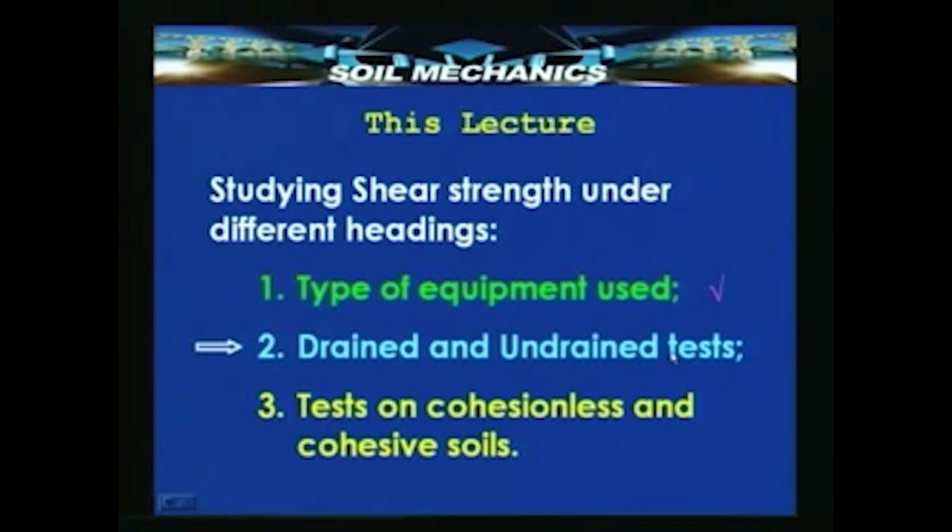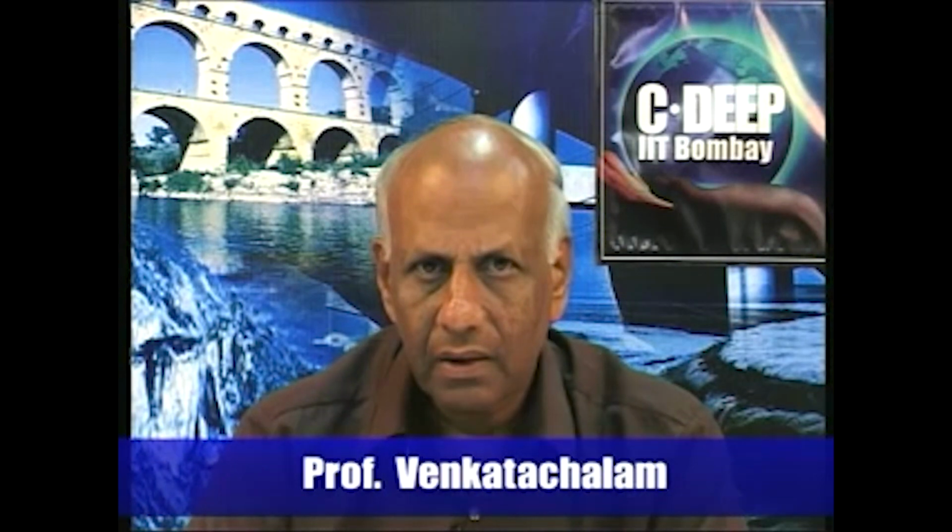Now, it is very well known, we have discussed it sufficiently often, frequently in both my lectures on consolidation as well as in this, that when a soil is saturated and when a load is applied, be it compressive or be it shear, whenever a load is applied, if the drainage is permitted, then the load gets transferred to the soil grains as intergranular stresses. Otherwise, they remain as neutral stresses in the soil in the form of excess pore pressures until the water drains off and the stresses are transmitted to the grains.